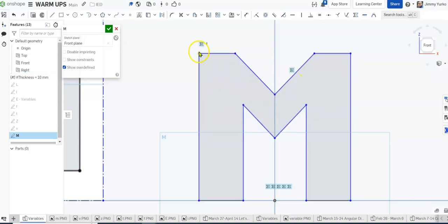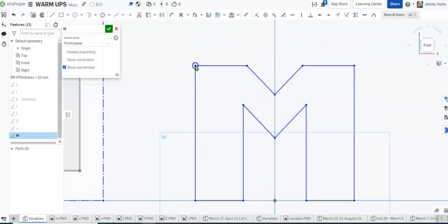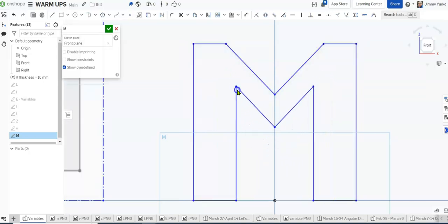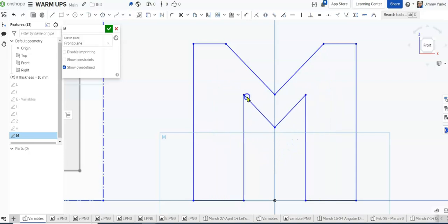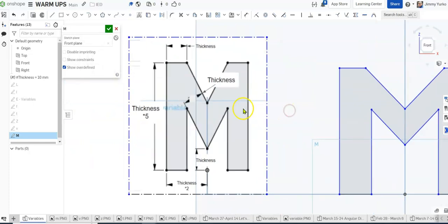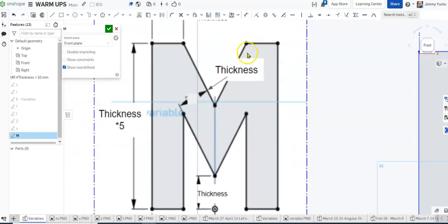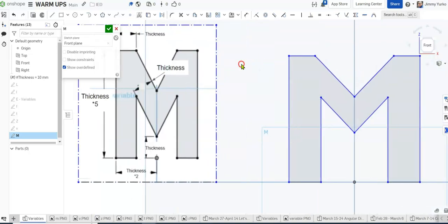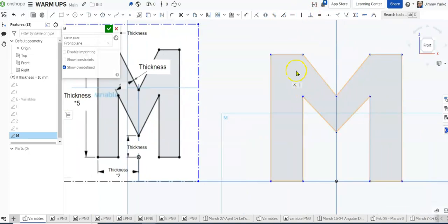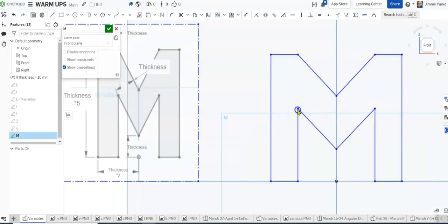So now those rules, everything lines up the way we want it to, except looks like I don't have a consistent line here. If I look back to our example, you can see that there is a vertical alignment between this endpoint and this endpoint. So let's go ahead and give that a vertical alignment between that point and that point, and escape from our vertical tool.